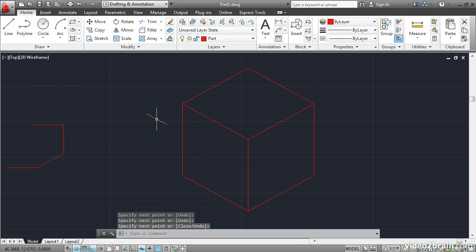So this is a 2-dimensional representation of a 3-dimensional object. You now know how to use Grid and Snap as aids to help you draw objects whose dimensions happen to be integer multiples of a given increment. Needless to say, not all objects in the real world are designed with integer measurements in mind, so Snap has limited utility. Snap is not to be confused with Object Snap, which is a different concept entirely.